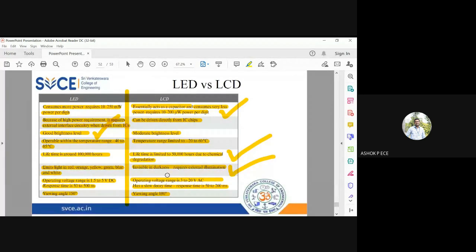And regarding light emission, in LCDs we don't have any color, because we don't do anything with lambda, the wavelength; we are just going to transmit or reflect light. If we transmit light, the liquid crystal becomes transparent. If we scatter light, the liquid crystal becomes opaque and dark, correct? So there is no concept of lambda in LCD. It is going to be white and dark, and even that is because of the applied voltage and the transparent and opaque nature of the liquid crystal display.